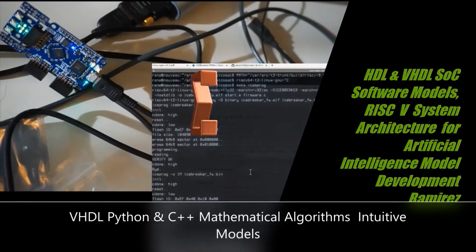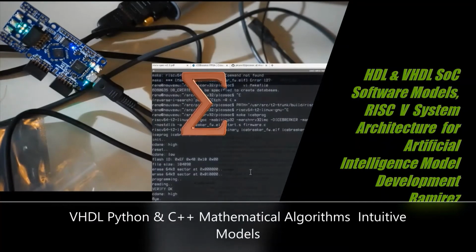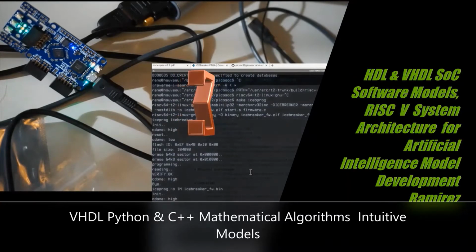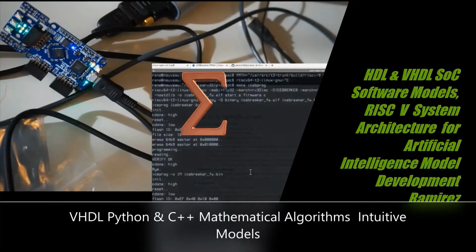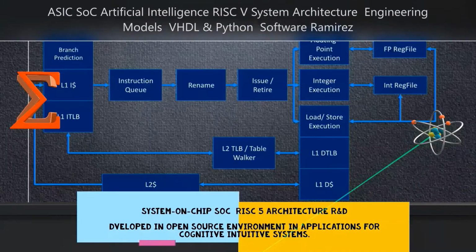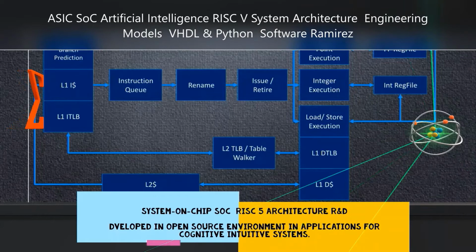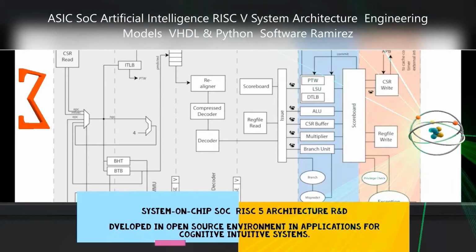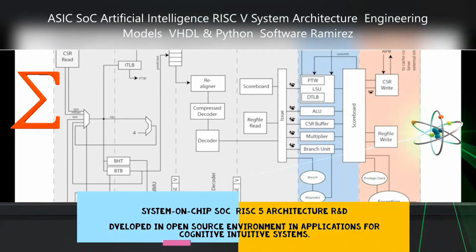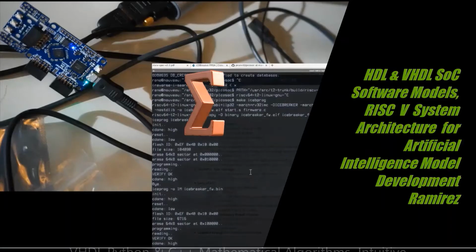Branches require the use of the arithmetic logic unit output to determine the next instruction address, which comes either from the adder, where the program counter and branch offset are summed, or from an adder that increments the current program counter by 4. The thick lines interconnecting the functional units represent buses, which consist of multiple signals.